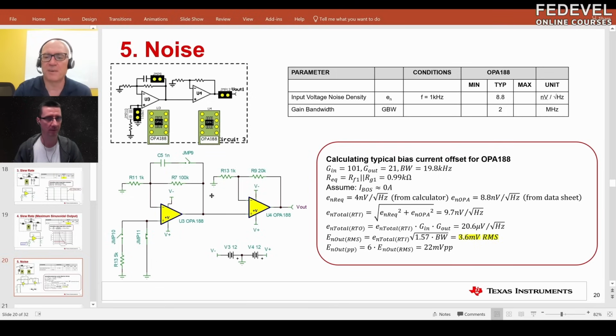And that's actually specified in the op amp. That's probably the major difference between intrinsic and extrinsic noise. Intrinsic noise is very predictable. You can calculate it, you can simulate it, and when you go to measure it, if it doesn't match the calculation and simulation, then something is not quite right, like there's some extra factor that you haven't accounted for. It normally will match. You should be able to predict it.